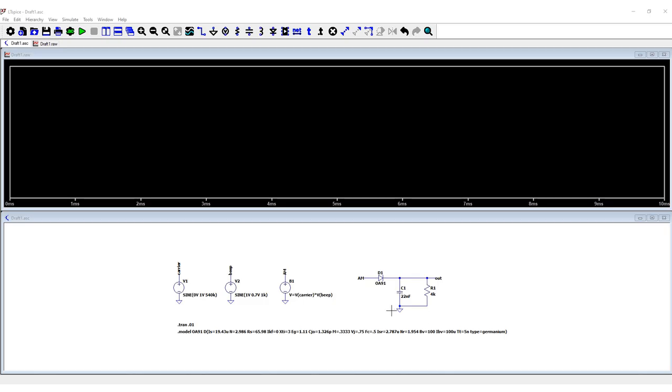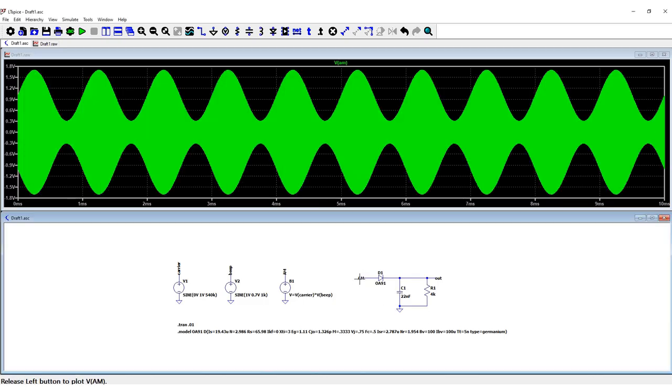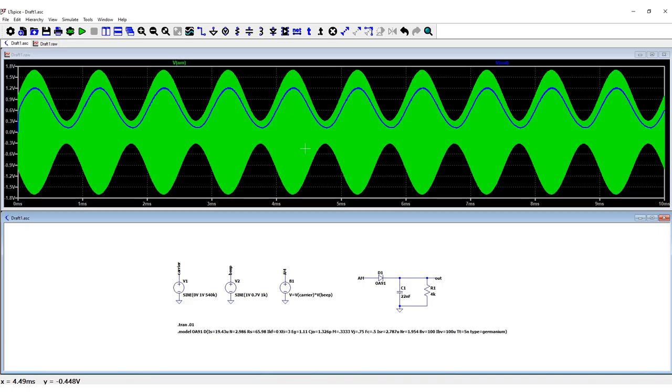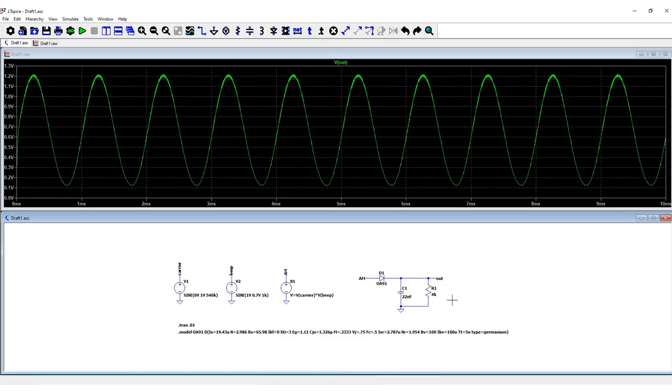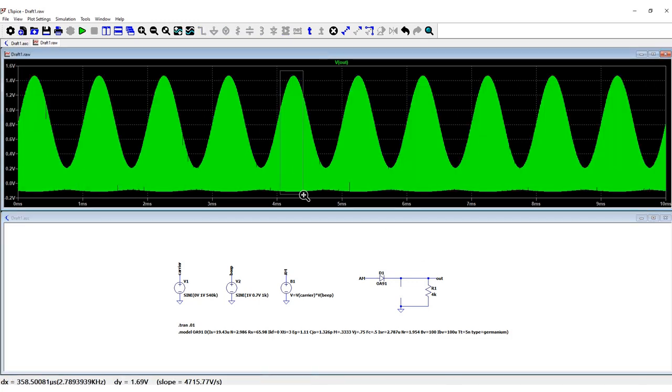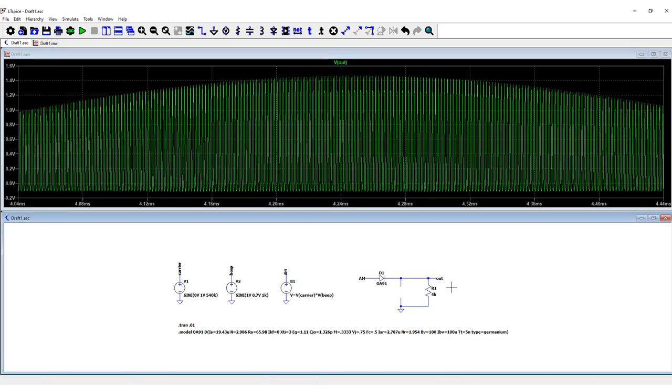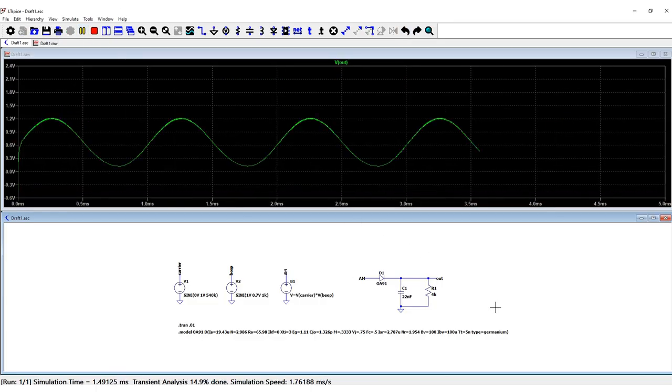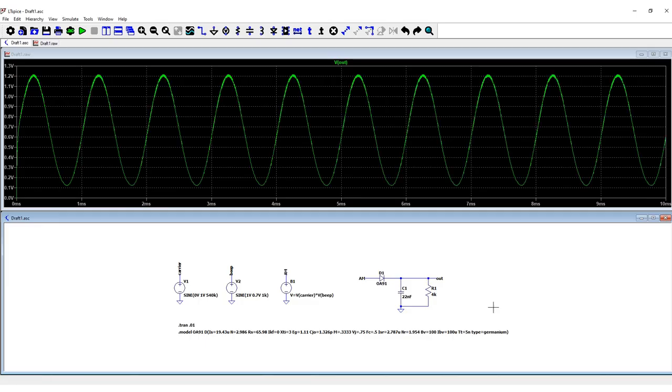So let's start. Simply speaking, the diode lets the positive part of the AC signal pass through, but blocks the negative part. Check it out. We can see the negative part of the signal is lost. It worked well. Okay, but if I don't have a capacitor, then what happens? I delete the capacitor. The envelope disappears and only the short pulses of the carrier remain. So the capacitor and its value are very important for demodulation.